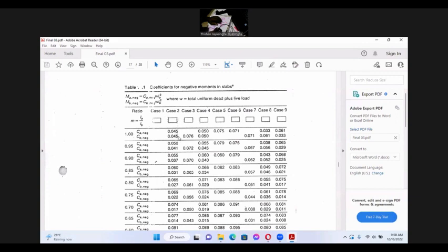But now let's say when you want to find the bending moment at the continuous edge, you can use these coefficients. And the coefficient is Ca negative W La squared, where W is the full load, La is the span, and Ca is the coefficient.